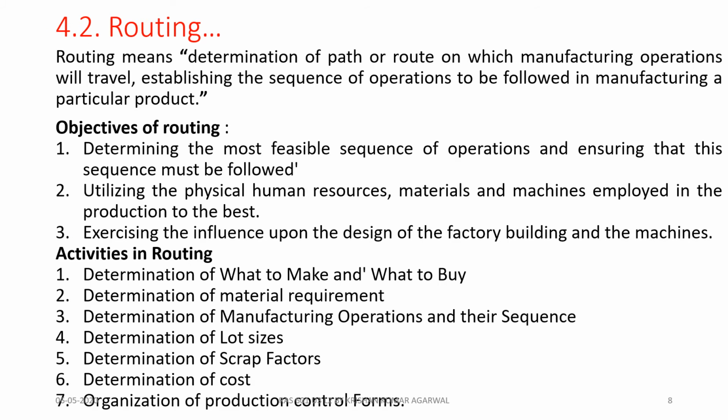Next function is routing. It's another important function, which means to decide the sequence of operations. We can say it is to determine the path or route through which the manufacturing operations take place on the shop floor, and establishing a proper sequence of operations on the shop floor is nothing but routing. The objective of routing is to increase the productivity.